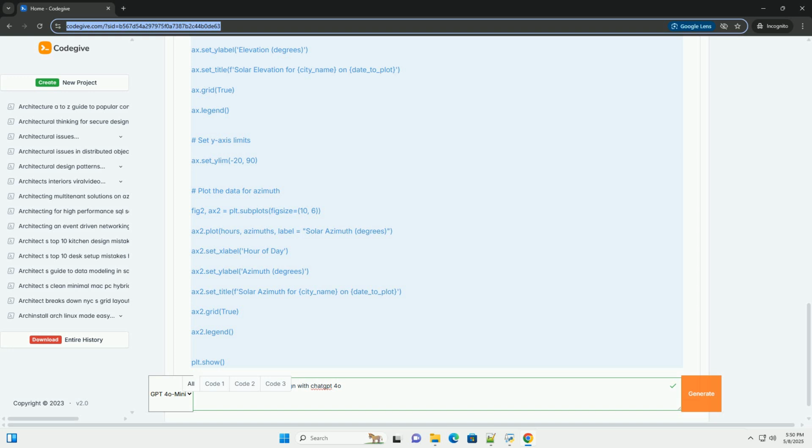5. Landscaping with native plants and sculptural elements: create a landscape design that complements the building's modern aesthetic. Use native plants that are drought-tolerant and require minimal maintenance. Incorporate sculptural elements, such as large boulders or abstract metal sculptures, to add visual interest. Use gravel pathways and permeable paving to reduce stormwater runoff. Consider adding a water feature, such as a small pond or fountain, to create a calming atmosphere.